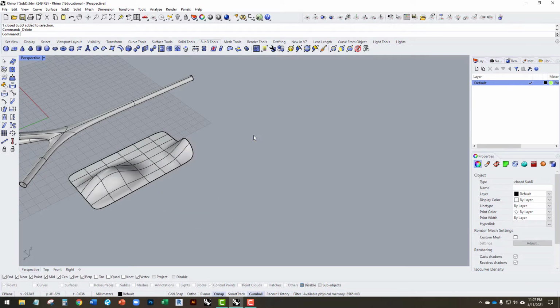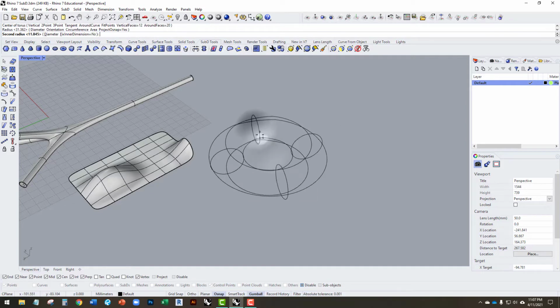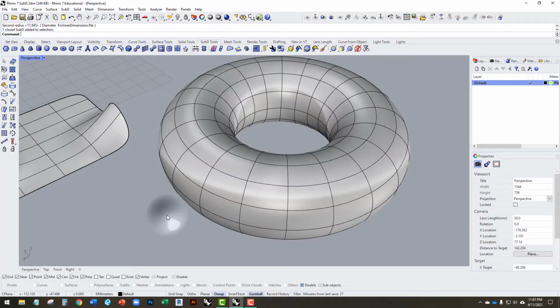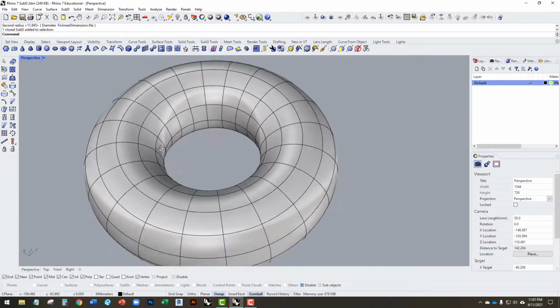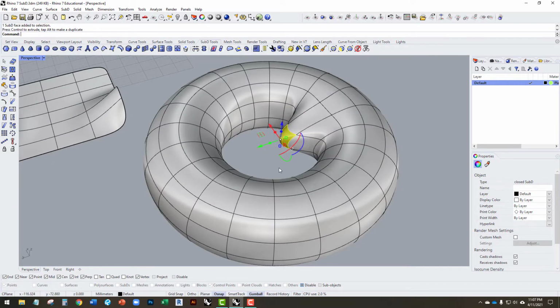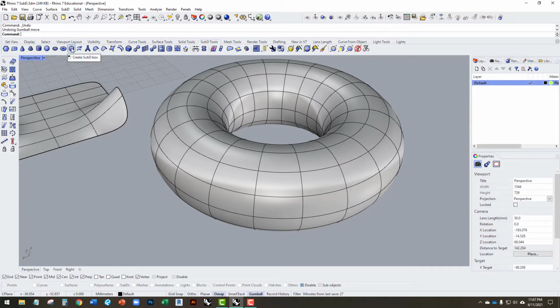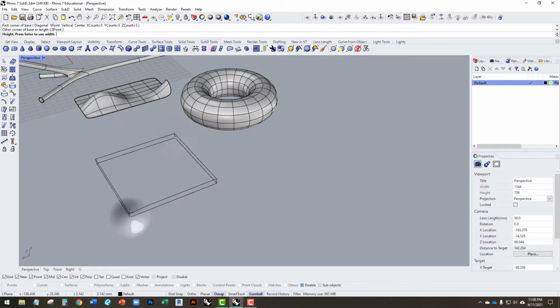We'll do this torus again, and when you click on it, it'll give you options. So we can select the number of vertical faces or round faces. We can make this more precise or less precise. I'll make this 20. Make the vertical faces 12. And this will give us more control over the geometry. The more subdivisions we select, the more control we'll have over the geometry. We can control it in local locations a lot easier. So a box like this can be made.